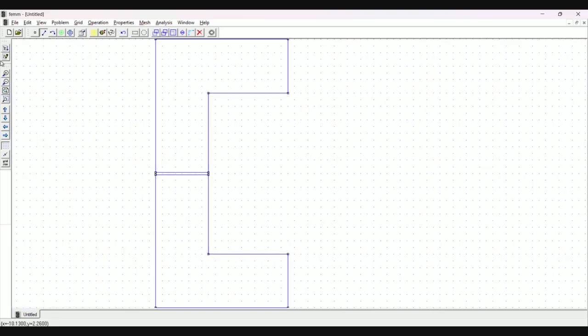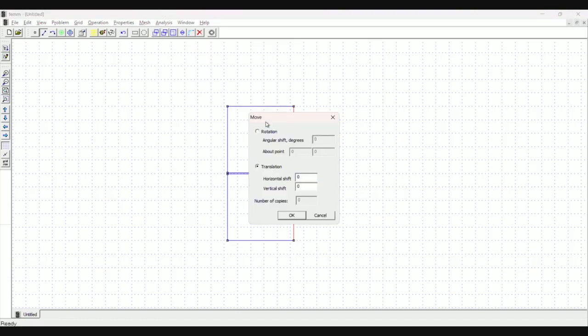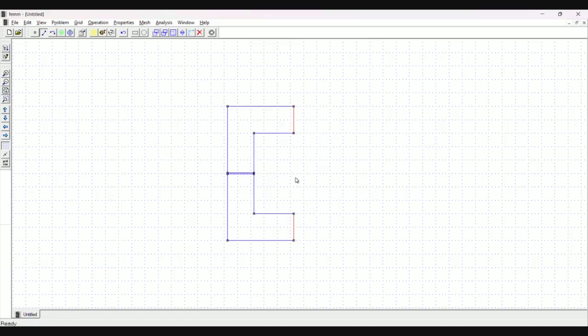And now I wanted to replicate this over this side. Okay, we forgot about the center limb. Center limb is also 2 mm width. So it means this, if you see, this is at 0, right? It's at 0, 0, 3. We don't want that. We actually need it at 1. X should be -1. This point should be at -1. I have made a mistake. So what we can do, we can just use the tool move, -1, right? And maybe I'll just delete this point.